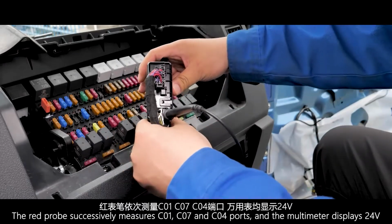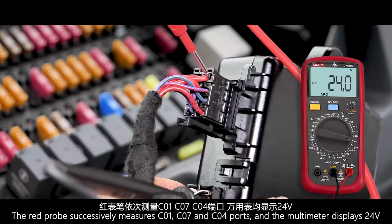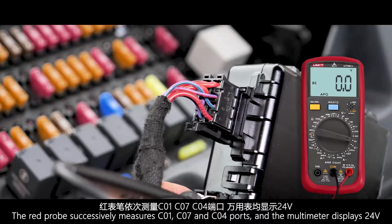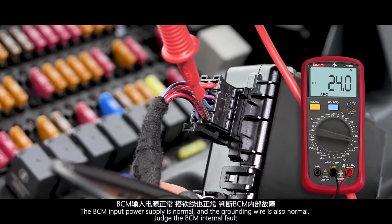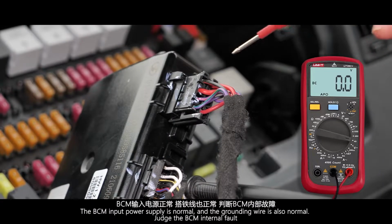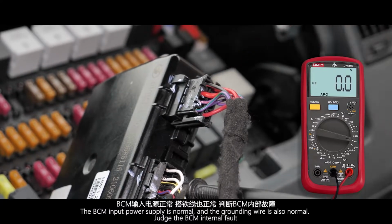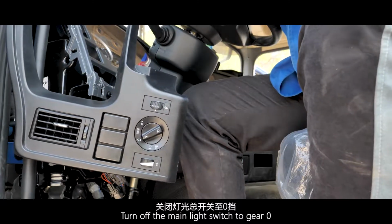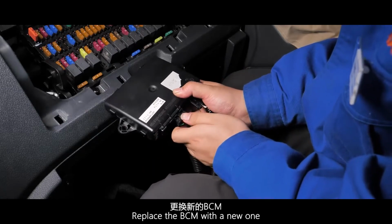The red probe successively measures the C01, C07, and C04 ports, and the multimeter displays 24 volts. The BCM input power supply is normal, and the grounding wire is also normal. Judge the BCM internal fault. Turn off the main light switch to gear 0. Replace the BCM with a new one.